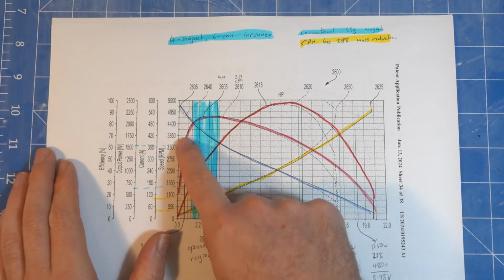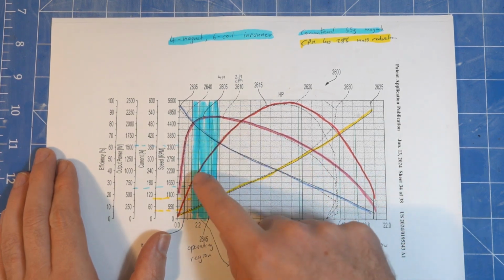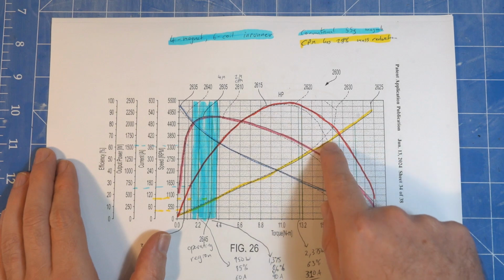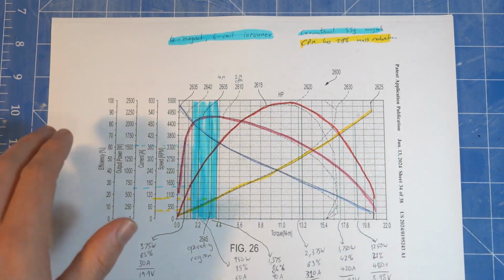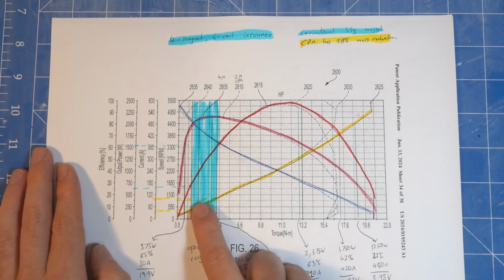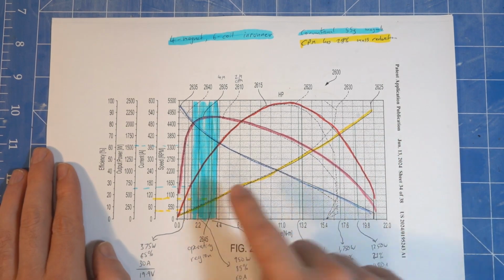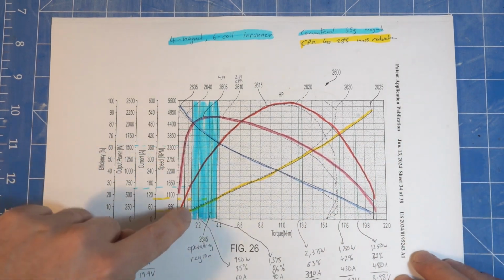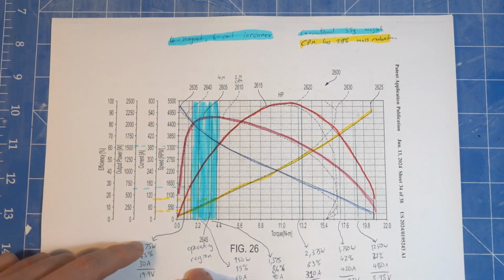It's hard to see, but the Consequent pole motor pretty much has an identical efficiency curve, and its power curve drops off a little bit quicker, but within the operating range it's basically identical. And then what's really interesting about this graph is they give us this extra line here for current. And I took a few little operating points. I took an operating point and got the power, efficiency and current.